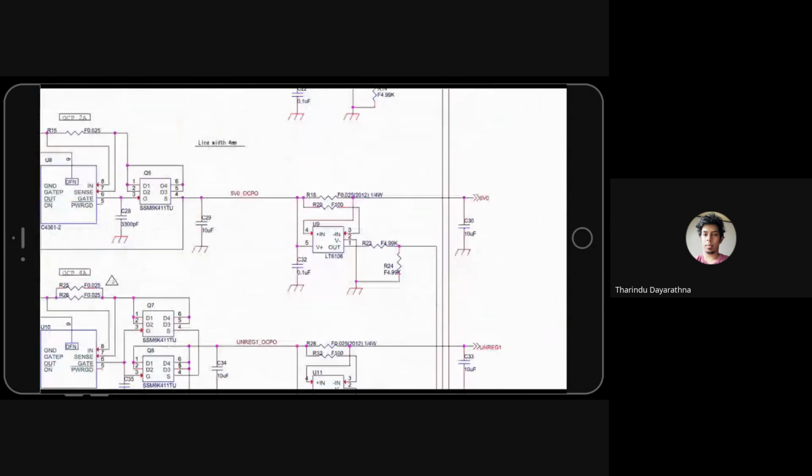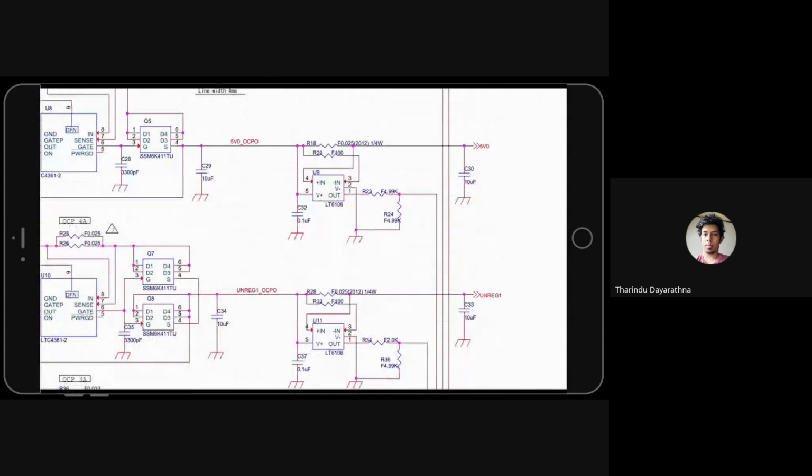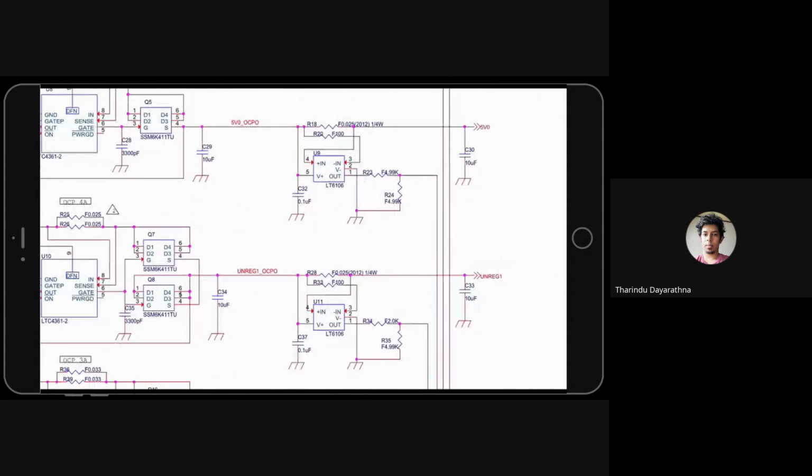One more thing. There are mistakes in this circuit. This was one of the initial circuits. Please remember, in the 5-volt line you have to take out this resistor, meaning directly solder it.